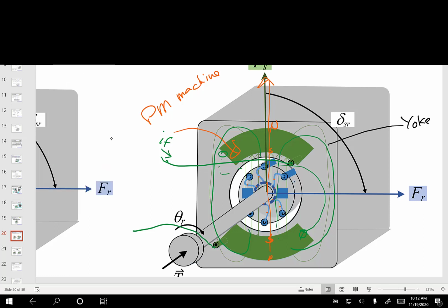And there's a little X right here, X, X. So everything on the top is always an X, and everything on the bottom is always a dot. And because of the segments, that current direction never changes. It's always with respect to looking at this thing. Even though the rotor's moving, the current's always going in on the top and coming out on the bottom, or vice versa.